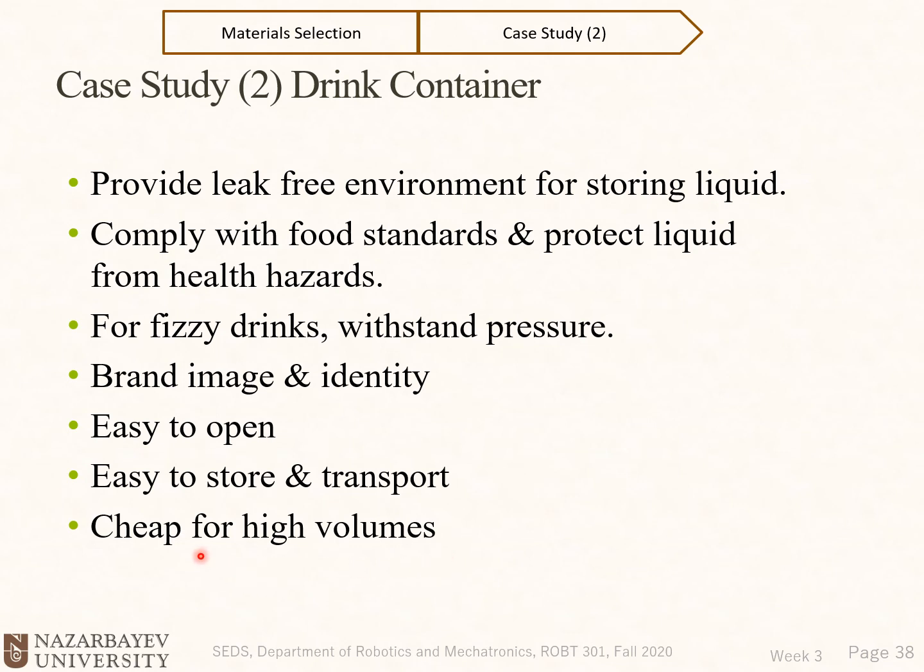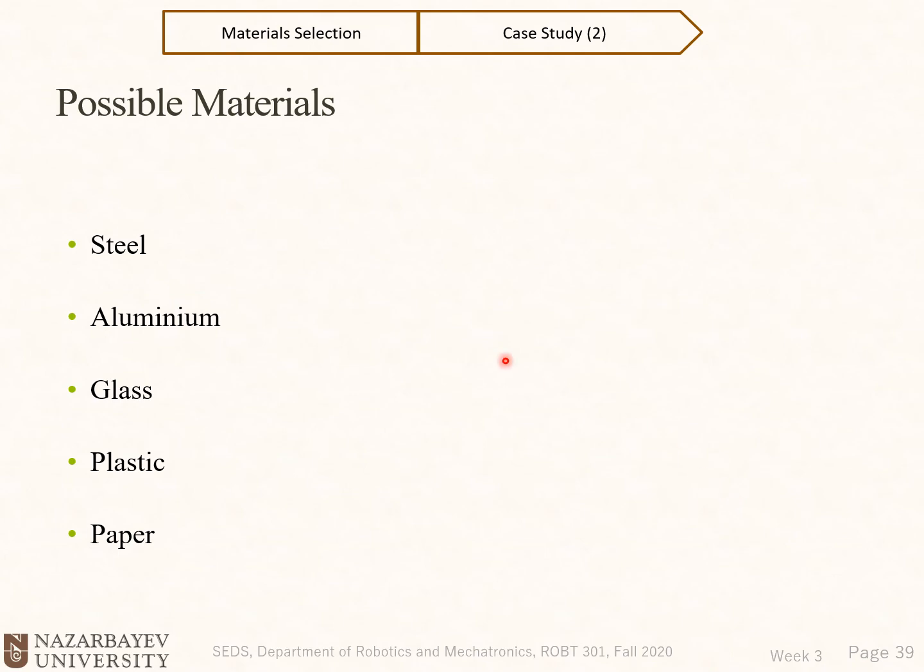Think about more basically specifications, yes? What are possible materials still? Aluminum, glass, plastic, and paper. Now between them, you could think of how you could choose one broad category. Glass, see if you could basically satisfy your specifications, or aluminum, still, what strength do we need to basically satisfy those requirements for the manufacturing? What Young's modulus do we need? Does it need to go through a cold working, hot working? And based on that, we need to select.